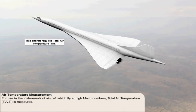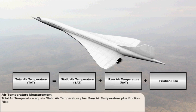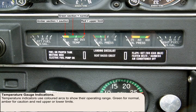For use in the instruments of aircraft which fly at high Mach numbers, total air temperature, TAT, is measured. The air is brought to rest, or nearly so, without the addition or removal of heat. Total air temperature equals static air temperature plus ram air temperature plus friction rise. Temperature indicators use coloured arcs to show their operating range. Green for normal, amber for caution, and red upper or lower limits.